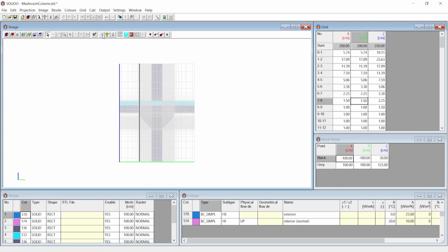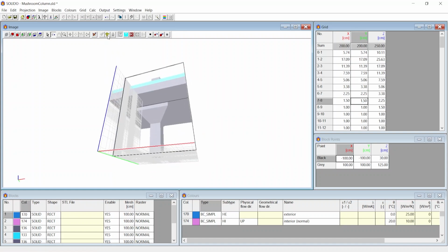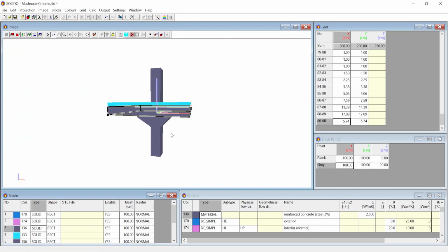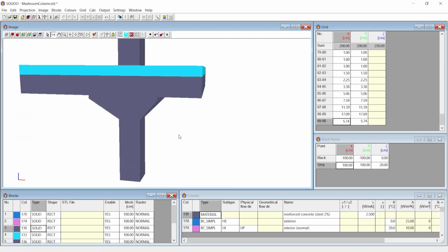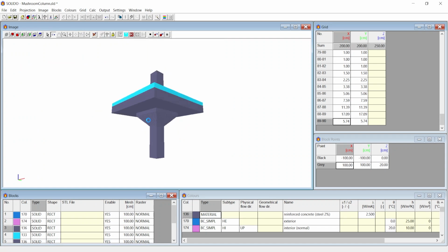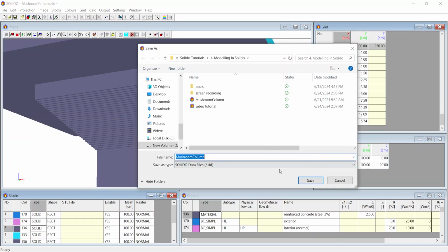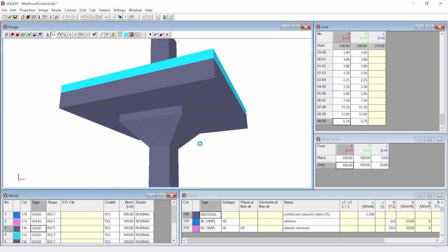Next, click on Fill Blocks to triangulate the mesh, then click on Rasterize. We now incorporate the sloped geometry after rasterization. Using Ctrl and H, you hide the selection preview and can visualize the object clearly. The object can be exported at this stage to Trisco if needed by saving as and selecting the extension .trc. It's important to turn on the selection preview using Ctrl and H, as it creates difficulty without the selection preview.